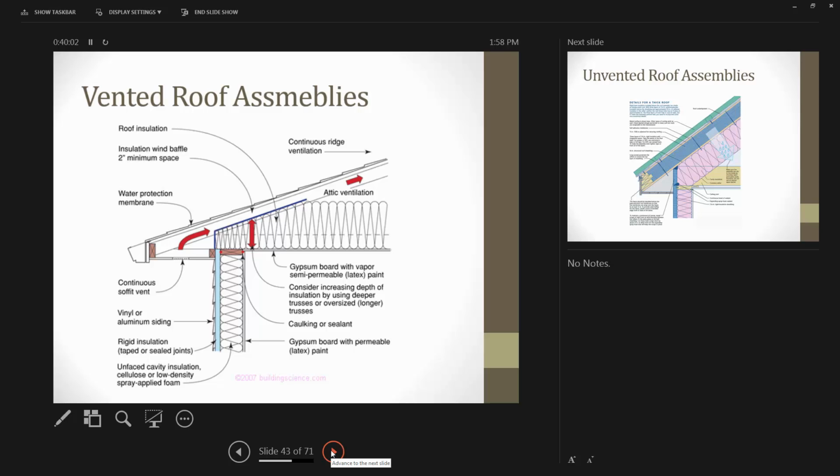It's also, and we'll talk about it in air sealing a little bit more too, and you'll see it in older buildings. It becomes an issue because in a heated climate, when you've got that heated air trying to escape, and it escapes up through the thermal envelope, and it hits the cold roof, what happens? It condenses. It goes from moisture vapor to bulk moisture.